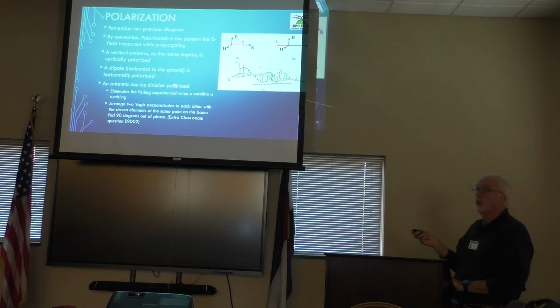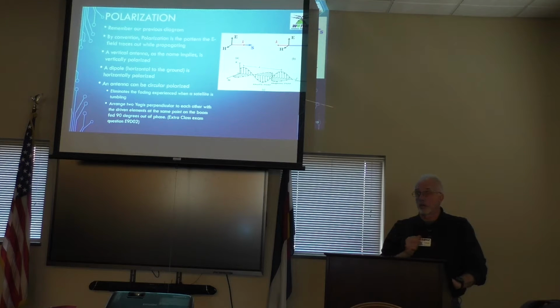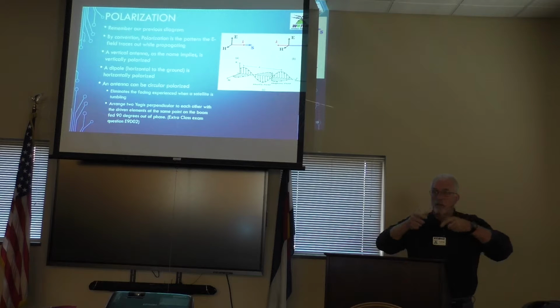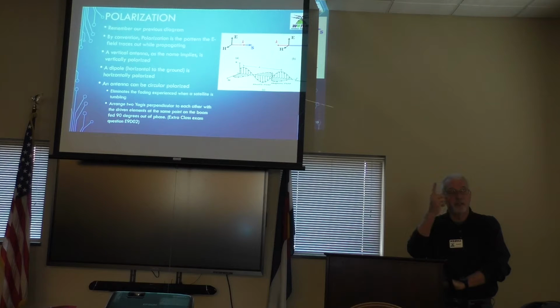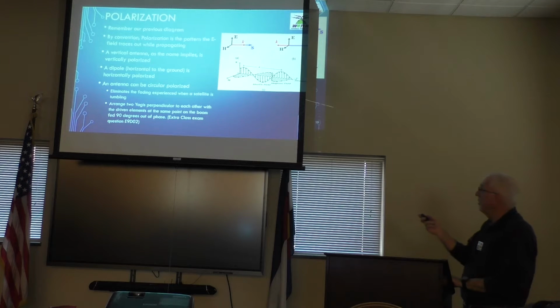Sometimes an antenna can or needs to be circularly polarized. Satellite operations, for one. These little CubeSats that are up there that are FM transponders or repeaters, transponder I think would be a better terminology for it, are tumbling. They're rotating. There's a little vertical antenna sticking out of that box, and its orientation is changing as that satellite tumbles. And if you've ever listened to a satellite signal on a polarized antenna, you will hear the signal fading, coming stronger, fading, coming stronger.